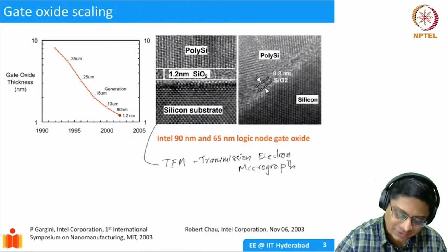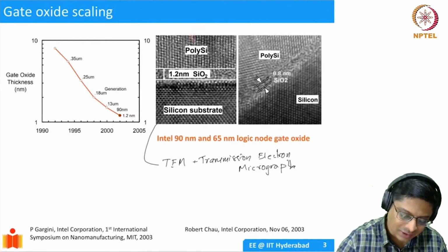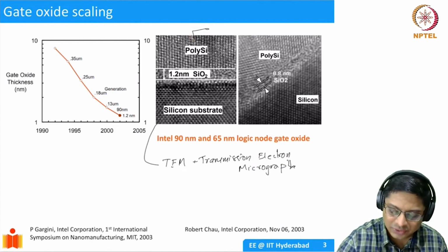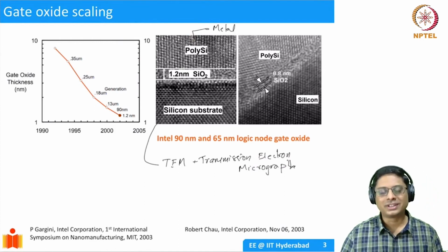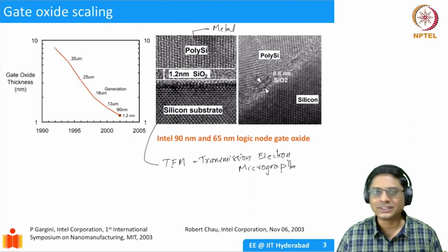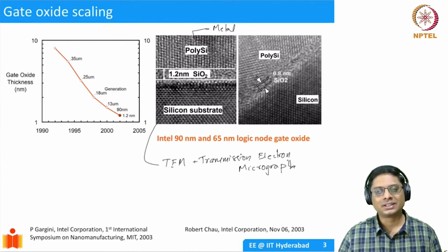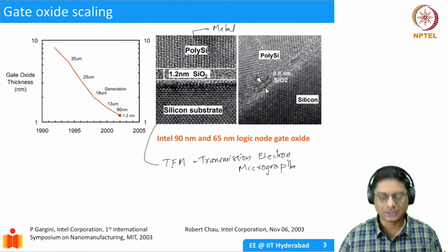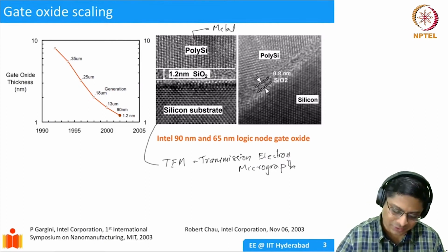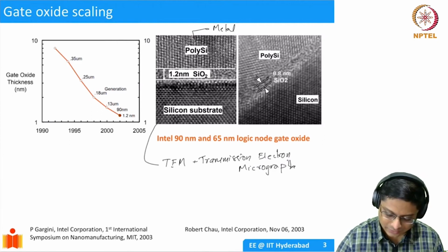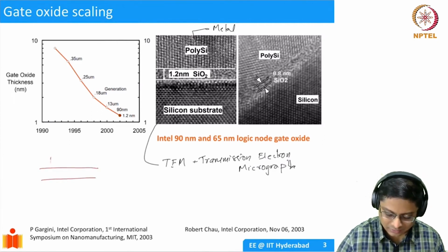And on top of it, in this case, what is shown is basically instead of a metal, we are using polished silicon. So in the origin, back in 1970s and 80s, we were using aluminum as a metal. Okay. So basically, what does a MOS capacitor consist of? You have the metal, which is some thickness, and then silicon dioxide, and then the bottom was silicon substrate.